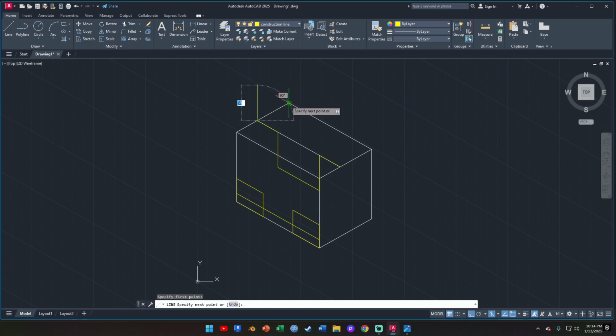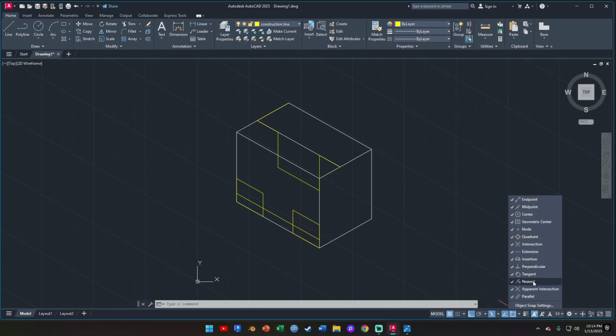So you draw your 38 mm here, and if you notice, I actually just drew that line on the left isoplane, right? The reason it still went on to draw is because of the snap-in, this thing here. If you have snapping on, and the program can choose the points and the vertices, then sometimes you don't need to switch the isoplane.